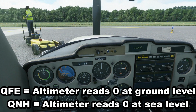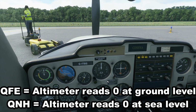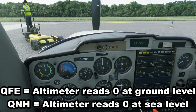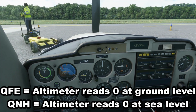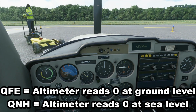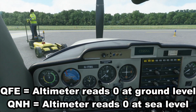Typically we'd either get the QNH from air traffic control, from an ASOS, which is basically an automated weather report, or we'd have previously looked up the QNH during our pre-flight planning. Also, if you know the aerodrome elevation, then you can use that to help set a rough QNH. And within the flight simulator you can also press B on the keyboard to instantly set the QNH on the altimeter.